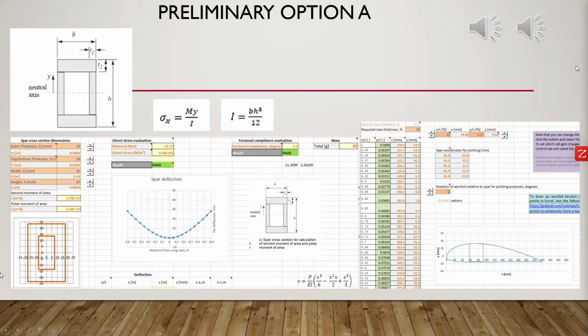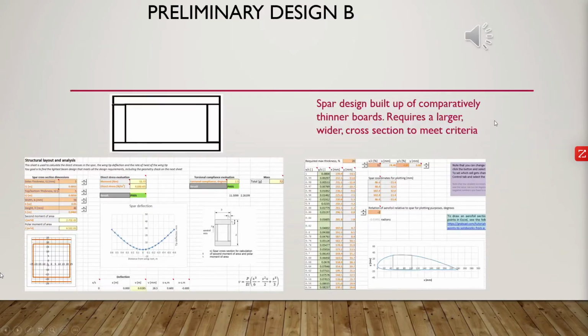Now that could only be done up to a point of 47 millimeters due to the constraint from the size of the rib. There were two approaches we looked into for cross-sectional design. The first one was a relatively narrow width, obviously again maximum height, but relatively high thicknesses, and then a taper that would reduce the thicknesses as the length increased. Option B, again maximum height, but this time we're going to make it very, very wide and very, very thin, both top and the sides.